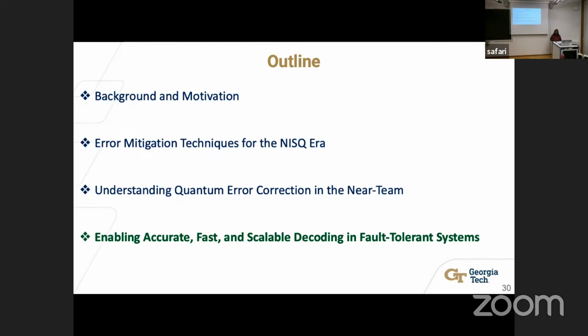It was a 7-stage pipeline. Depending on the frequency we could clock it, we decided a frequency. It was a fully pipelined design, and 42 nanoseconds was the maximum that we could clock it at, but somewhere really faster than that. Does it answer your question? Actually, I think I have a backup slide. I can talk about it later, but basically, depending on the decoder configuration, things change. The rest of the logic also needs to work, and that determines the frequency. So it's something around that. 42 was for distance 5, which is way faster than what I was asked to do.